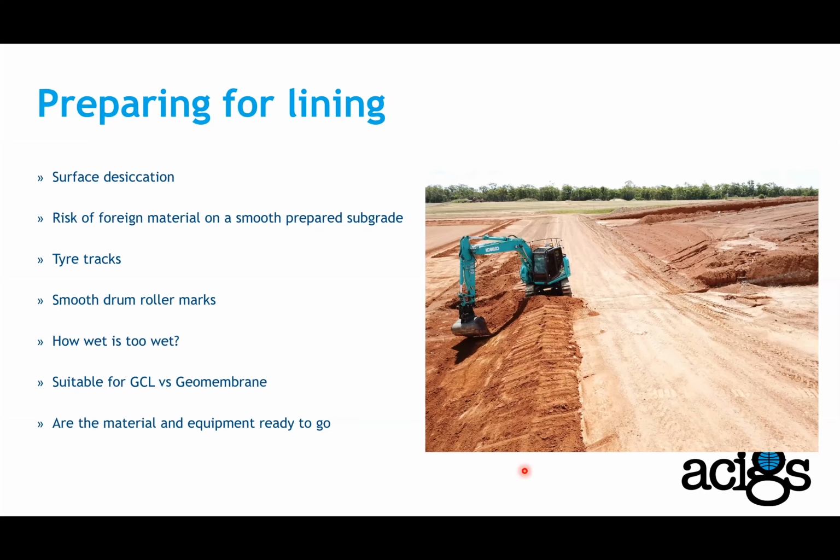And also the other important factor right at the bottom here is, are the material and equipment ready to go? So we see a lot of times that the construction for the subgrade is completed, but the material or equipment for the lining is not ready to go. Then it just takes a rain event to, you know, make a lot of damage to the subgrade and has to be reworked.